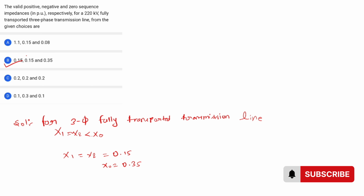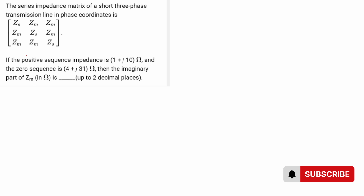Come to the next question. Given that a series impedance matrix is given, the positive sequence impedance is 1 plus j10 and the zero sequence impedance is 4 plus j31. Then we are asked about the imaginary part of Zm.